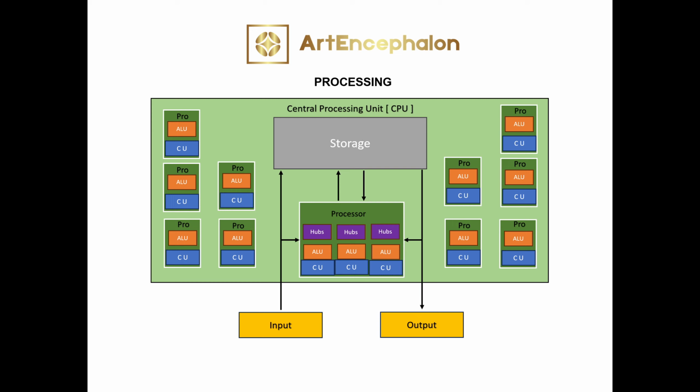And now, what they have is a CPU and the platform control hub put into a package. So if you open that package, you are going to find 2 dice. One is the CPU, and then the other is the platform control hub. AMD had its own. They just called it, then it used to be Fusion Control Hub. Later, they changed it to a chipset. So you can have different types of arrangement.